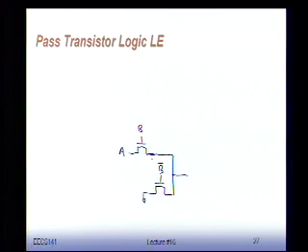Well, we have a resistance here, but what's the resistance at the A side? It's very hard to figure this out. I cannot figure out how to solve the RC time constant of this. I don't know where to start. Why is that? Because there's no connection to VDD and ground here at the input.